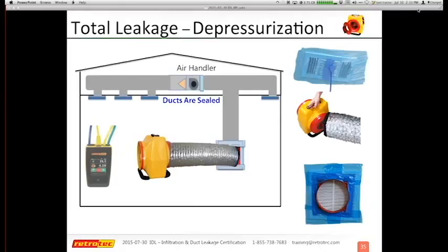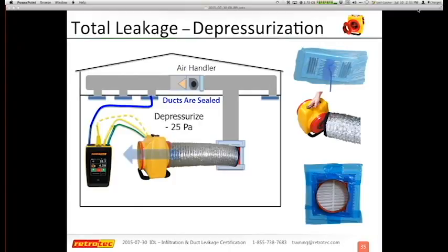All right, so you connect your gauge. There's a blue tube that will go to, usually, the register nearest the air handler. It doesn't have to be, and your goal is to make sure that you're actually getting pressures further away from the system, to make sure there isn't anything clogged or a significant issue. Connect your tubing and speed controls to the system itself, and you depressurize to 25. Basically, just tell it to set pressure 25.